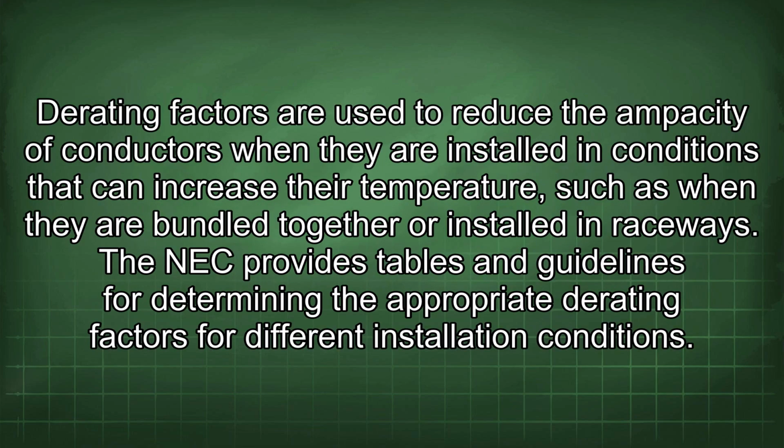Derating factors are used to reduce the ampacity of conductors when they are installed in conditions that can increase their temperature, such as when they are bundled together or installed in raceways. The NEC provides tables and guidelines for determining the appropriate derating factors for different installation conditions.